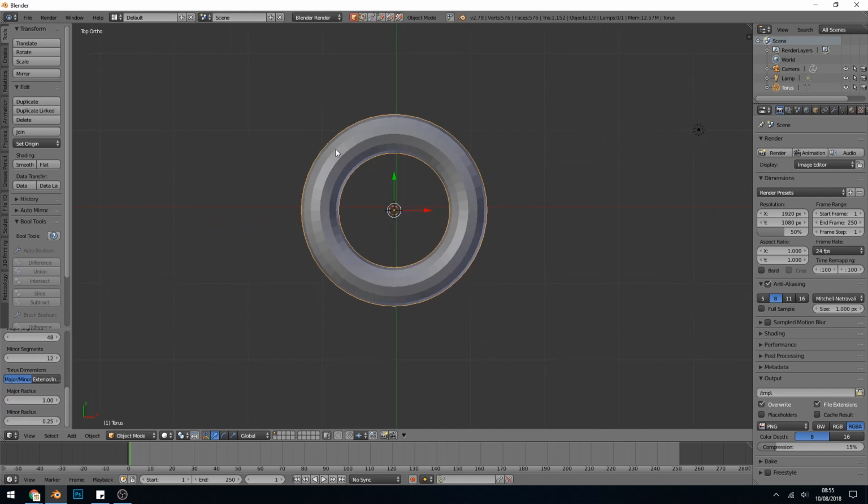And this is a very big curve on a pipe. I'm only going to take this section and then I'll extrude those two edges out, and then it's a nice curved pipe. But I want to make it a bit fatter and shorter, and I want less segments. So if I bring this right down, so it's still got a bit of a curve, but it's got that low poly feel. A number divisible by 4 is good, then you know that it's going to be cut off here, and obviously 27 isn't, but 28 is.